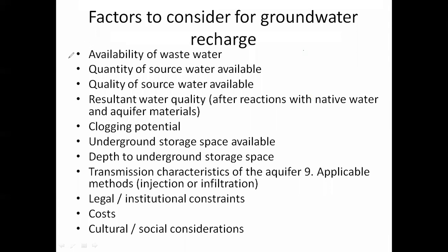You already know one example: in lakes, the groundwater level is higher, and in other places it is low. So the availability of water is also important, and the availability of wastewater is also important. Why? The wastewater will pass through open drains, right? Open kucha type like this. If it is soil, obviously it will infiltrate, right? Soil is a good filtering medium, so it will infiltrate this wastewater, and ultimately it will reach the groundwater. So like that you have many things. We'll try to see them one by one.